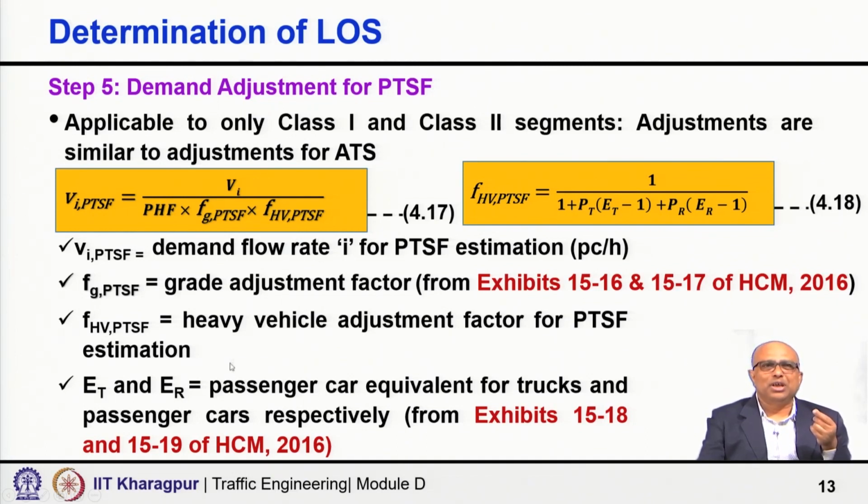Here also you can see the PHF, peak hour factor, you can get directly. And f_HV,PTSF is the heavy vehicle adjustment factor, for which we again use equation 4-18.